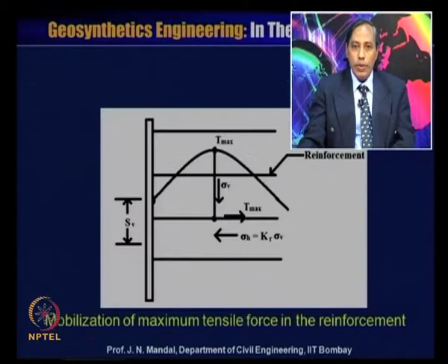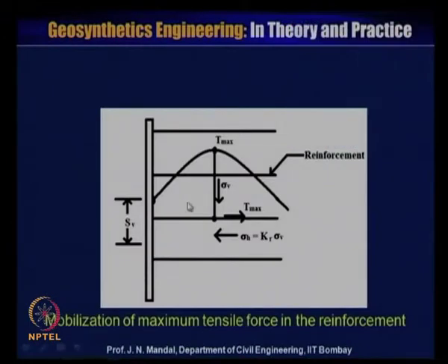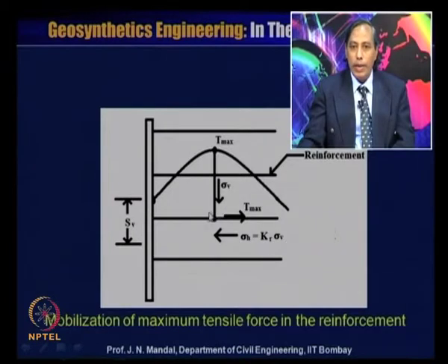Now, at any point you can see here that this is sigma of V and this is sigma of H, that is Kr into sigma V, and this is T of maximum, the tensile force acting here. This is the mobilization of maximum tensile force in the reinforcement, and this is the reinforcement.